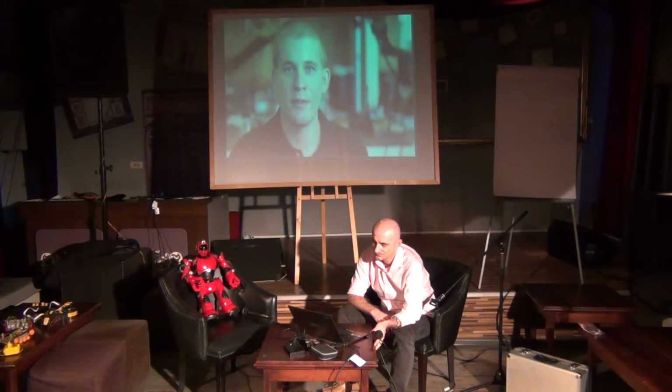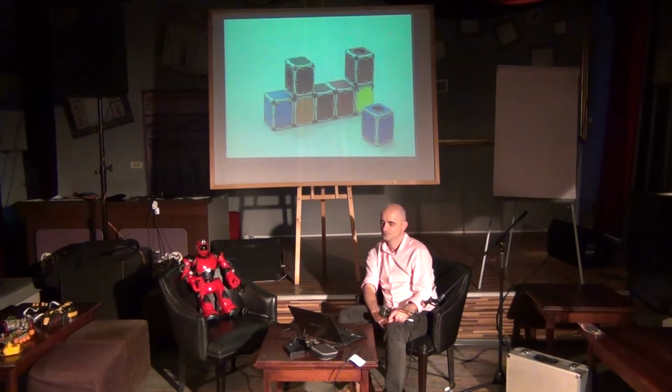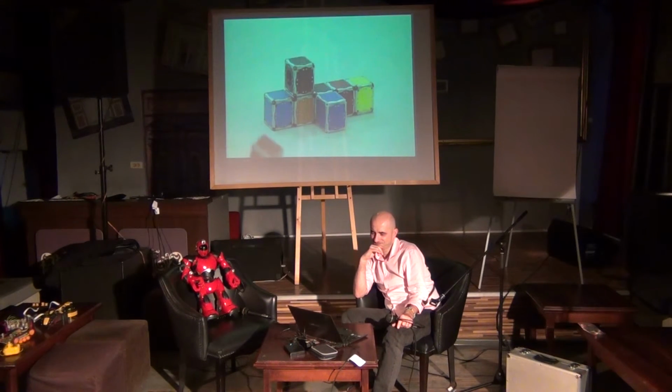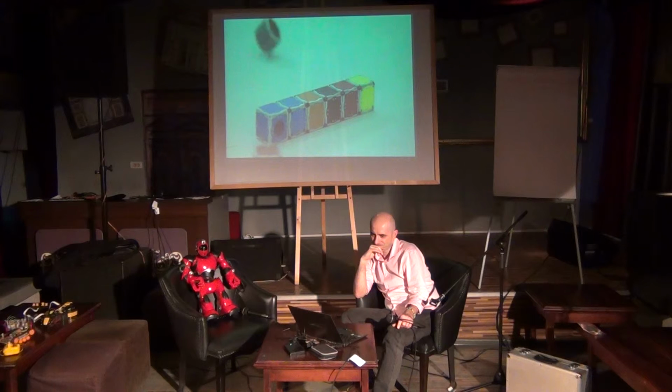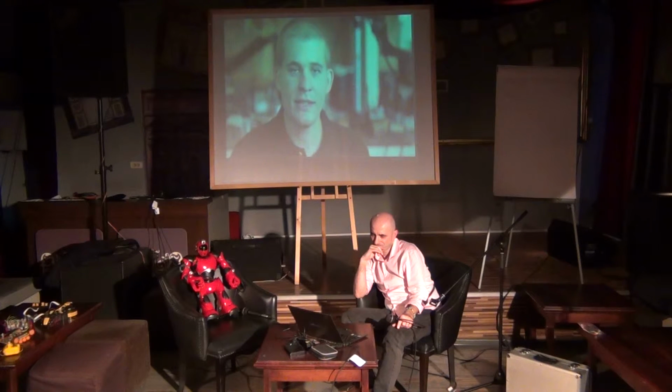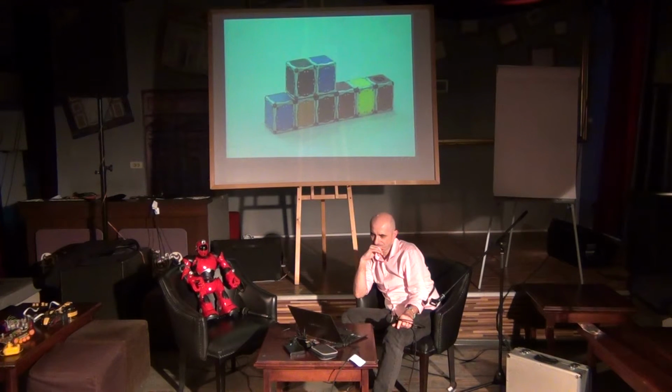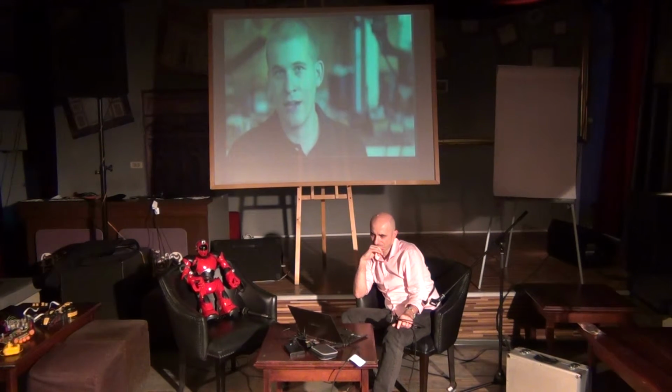Up until now, most other modular robotic systems use servos and motors in order to have arms and attachments that move modules into different places. However, we wanted a simpler approach that uses fewer actuators, fewer moving parts, and was easier to implement on a lot of different robots. And so the approach that we chose is to use angular momentum. And essentially what that means is there's a spinning mass that spins inside of the robot. We want the robot to move, it stops that spinning mass, which takes that motion from the mass and applies it to the robot. And a part of this that's unique is that the spinning mass is completely inside the robot, and so the robot doesn't have to be in a certain position in order for the force to be acted upon the robot. And so this allows for a lot more types of motion with only one actuator.